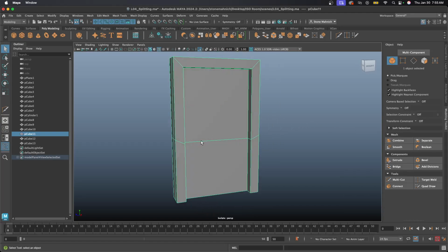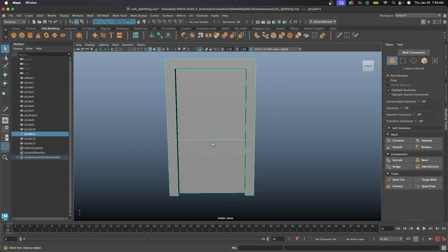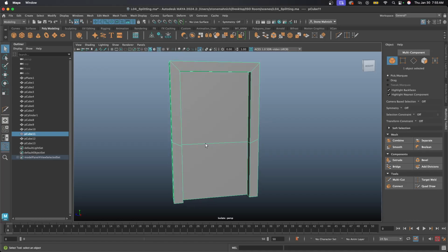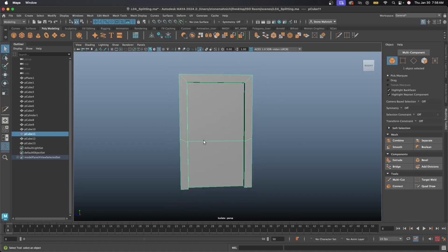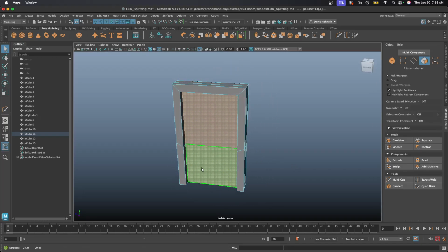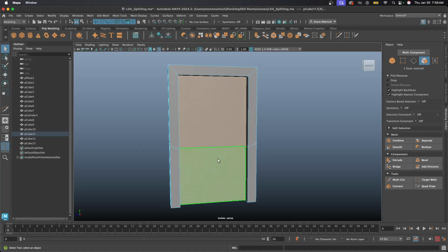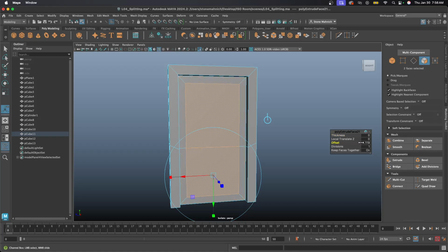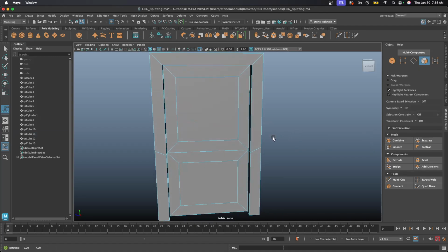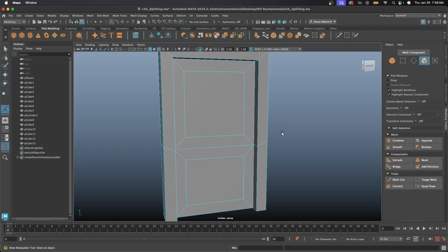So yeah, you should have an edge loop. You should have a line across this. If not, let me know. So yeah. Then let's go to our face mode and select these two faces. So right click hold, face. I'm going to select the two front faces. So see, nothing else is selected. Nothing else should be selected, just the two front faces. We're going to extrude them to offset. I want to keep faces off.